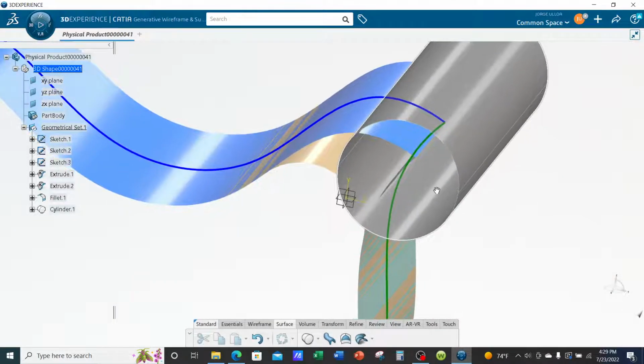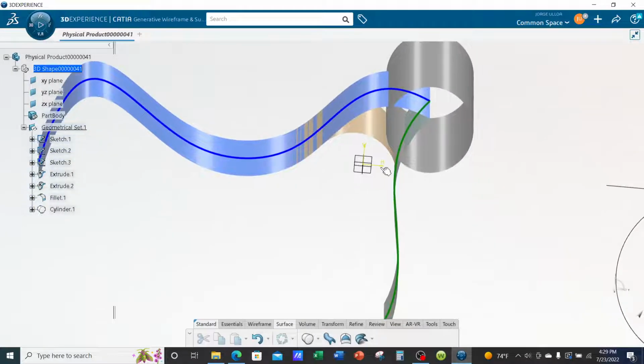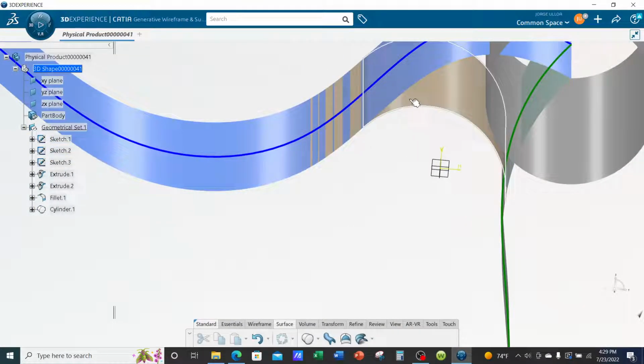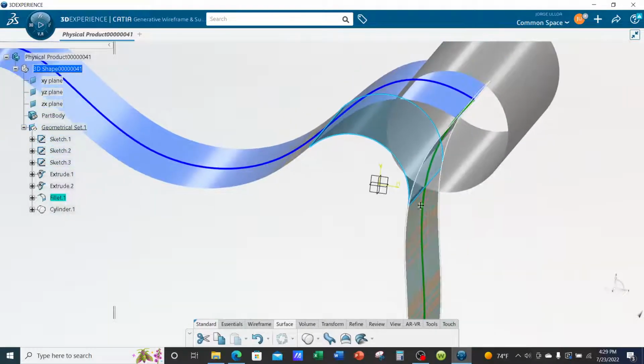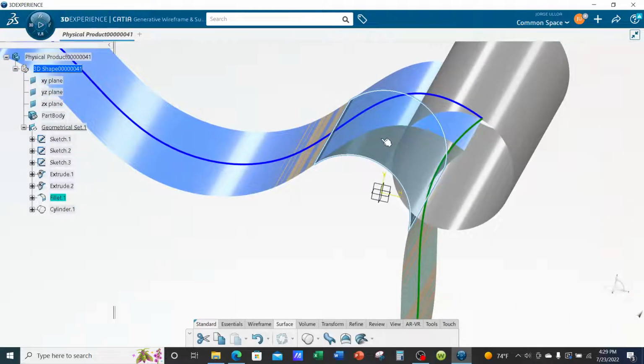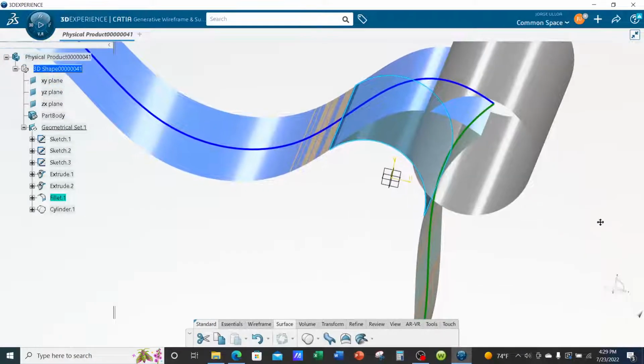So we've created a cylinder. And one of the things that you do want to do is you want to at least go up to that tangent line of the fillet or go beyond it. So instead of having a tight turn, you can take this tangent line and move it further back and start transitioning from back here as you transition over to the green surface. Typically what you'll do is go further beyond, start off a little flat, and then you start rounding off. It's just a smoother transition.